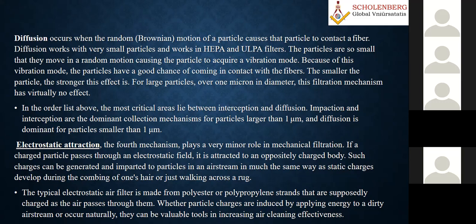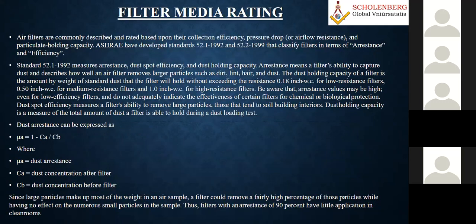So these are the four mechanisms. Based on that only, the filter media rating has been done. Filters are commonly described and rated based upon collection efficiency, how much filtration, what diameter, and depending upon the efficiency, they also give the pressure drop, because we then have to select another machine called a blower or fan.